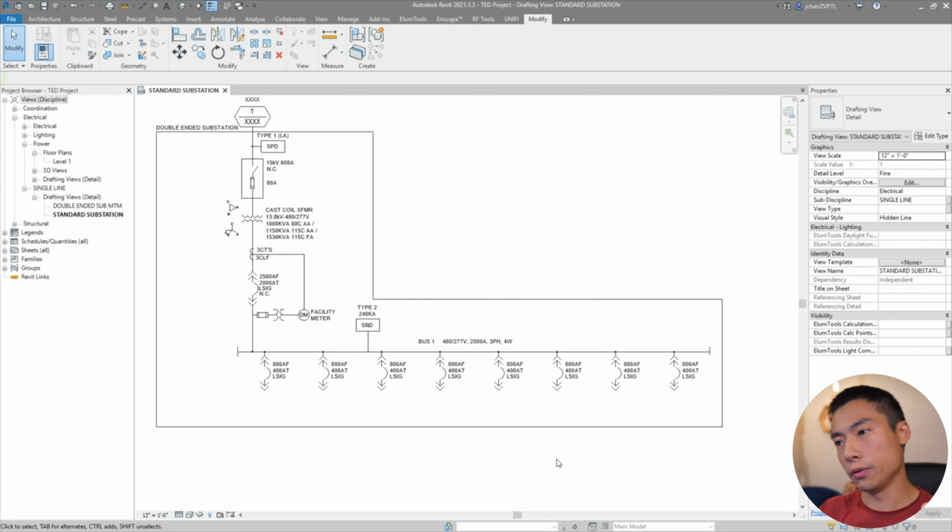Sometimes maybe if a chiller is really big, then you would run a chiller directly to a substation. But unless that thing is like, I think, a 1,200 ton chiller or something like that, that's what ended up going to a substation. If it's anything smaller than that, you typically might take it to a motor control center or a mechanical panel. But anyway, this is the most basic substation that you could use. You have a single feed coming in, you step it down, and you send it out.